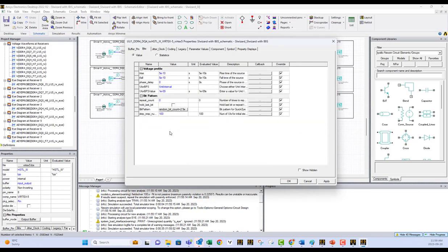And now you have to specify the rising time, the fall time, what kind of signal, the bits per second, how many bits per second, the PRBS. You need to specify the PRBS. And all the other information that's supposed to exist in the IBIS model, you need to specify them manually now.